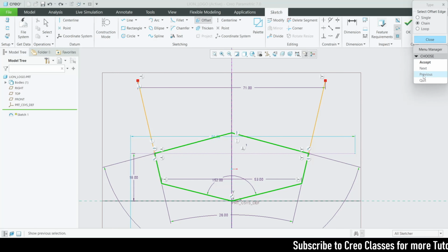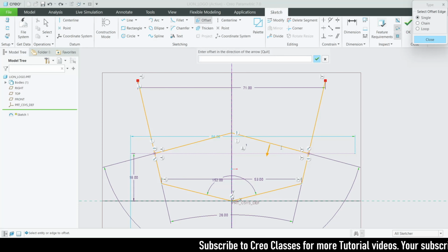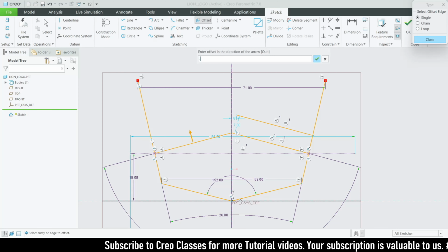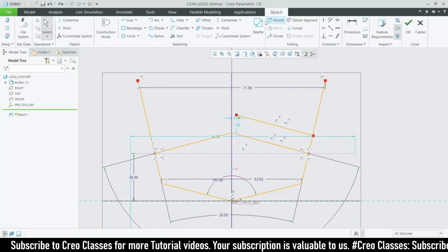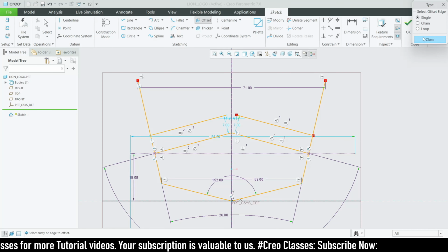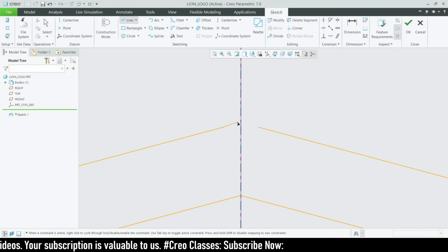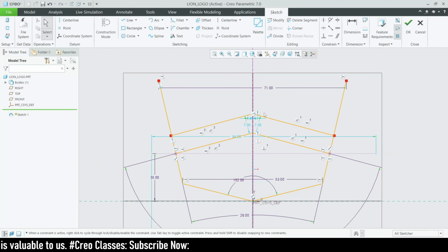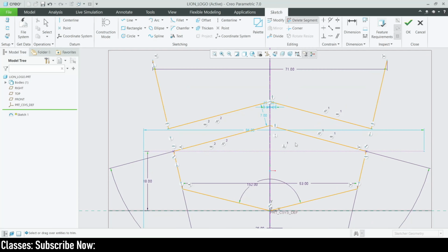Okay, I don't want this, I just want to quit this. Let's go for the single itself. This will be -7 towards outside, and this will be -7 towards, oops sorry, this will be +1, sorry, I had not seen the arrow mark. Okay, so this will be 7. Close this, and I'm just going to draw a line like this and a line like this, and we don't want these segments, since this will be a hollow feature, right?